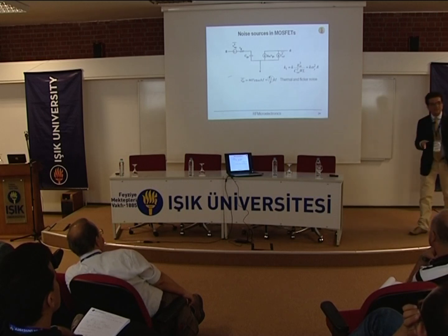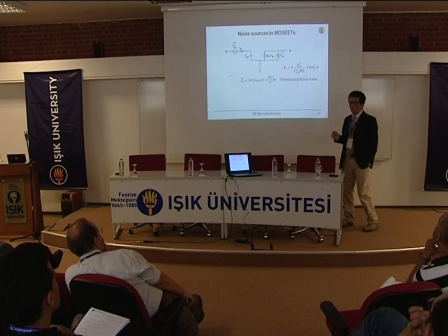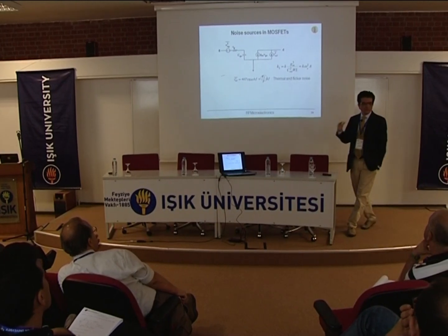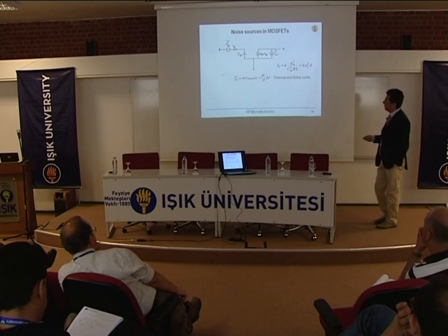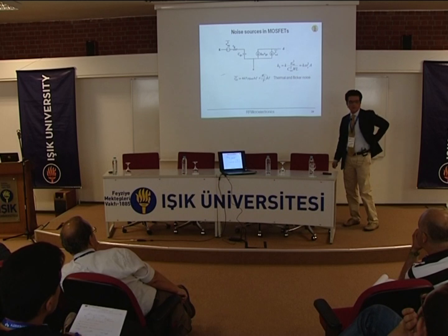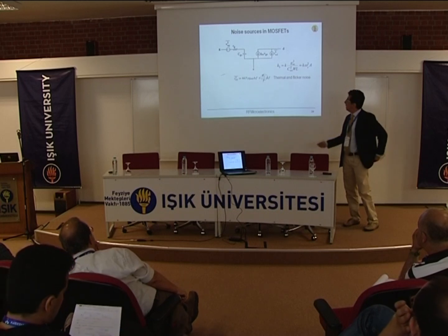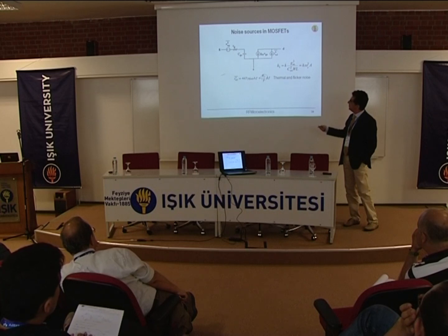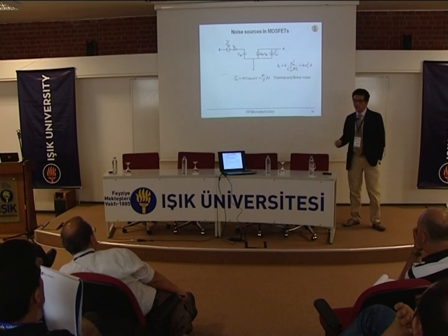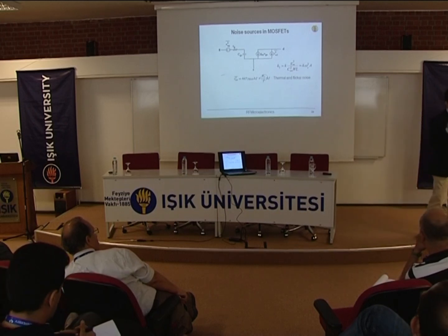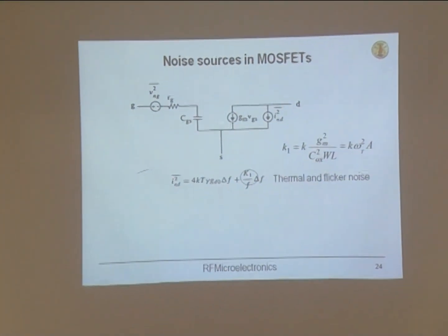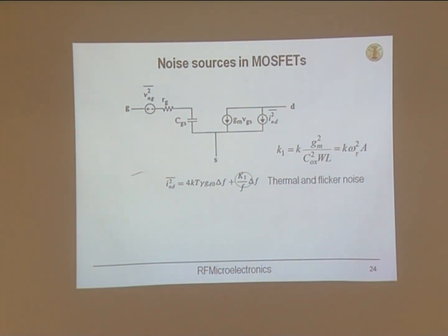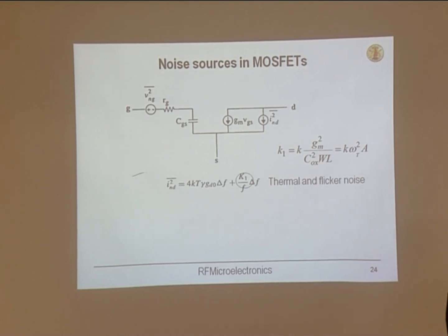Okay, this is the actual expression of the thermal noise of a device. Then we can demonstrate that this is, especially in a long channel device, equivalent to the gm, the transconductance of the device itself. Plus we have a 1/f noise component, which means that when we look at the energy of the noise close to 0, we find an increasing energy. And this is described by this 1/f component. So I just remind you this noise expression because we will use it to determine the quality of